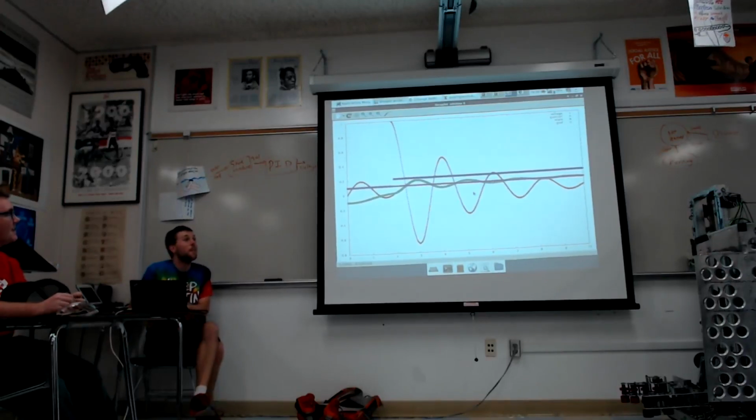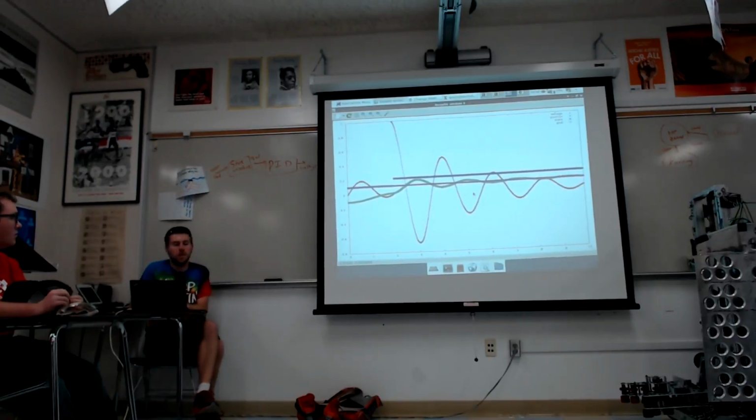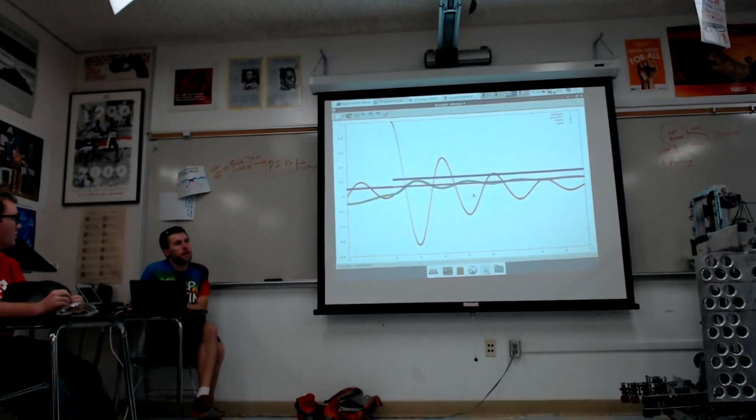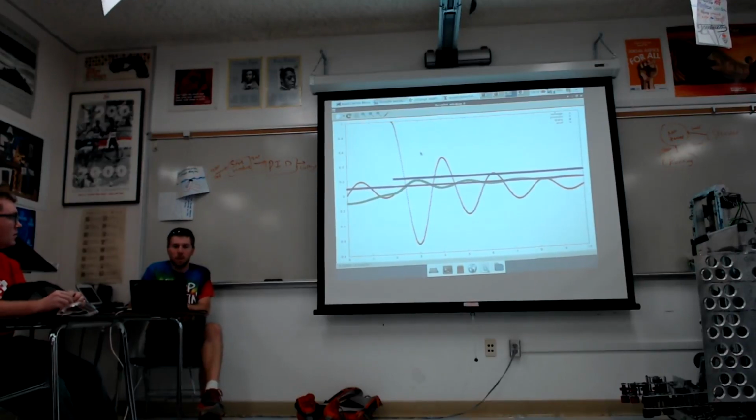We got that. Wouldn't you have to decrease the voltage with this oscillation? KP decrease. It's actually the flip. We need to add damping. They're equivalent statements. We don't have any damping in our system right now. But it's also too slow. Fix that. So let's go add some damping.